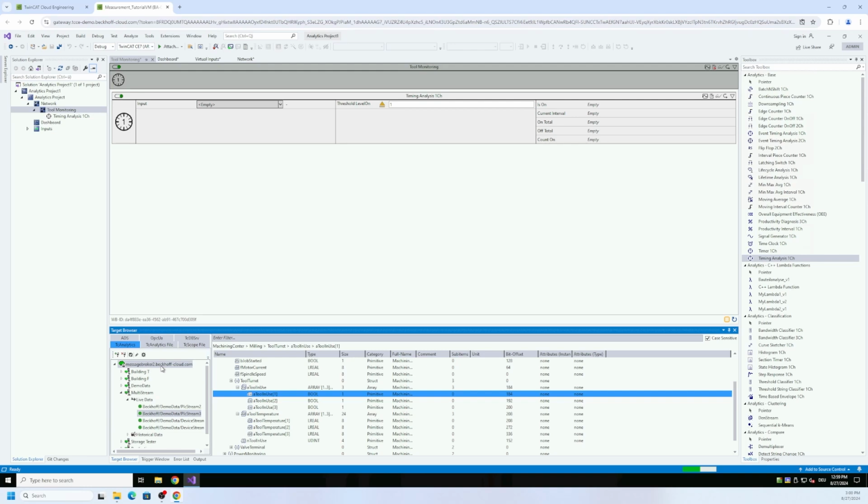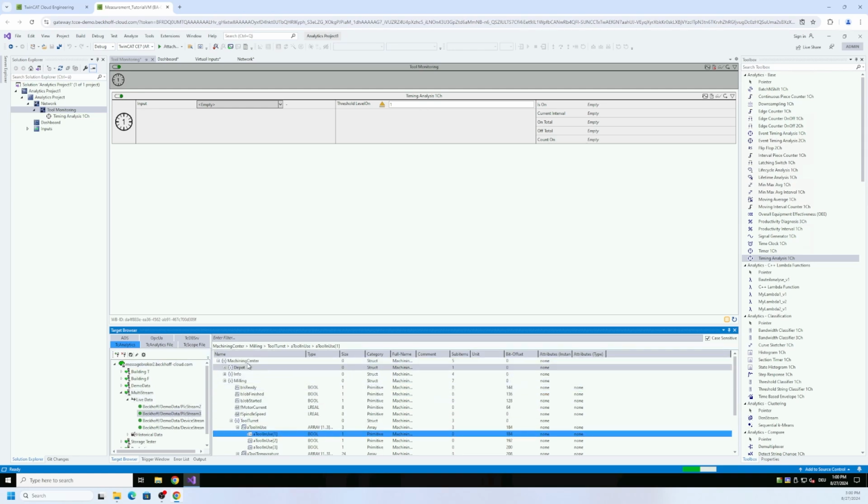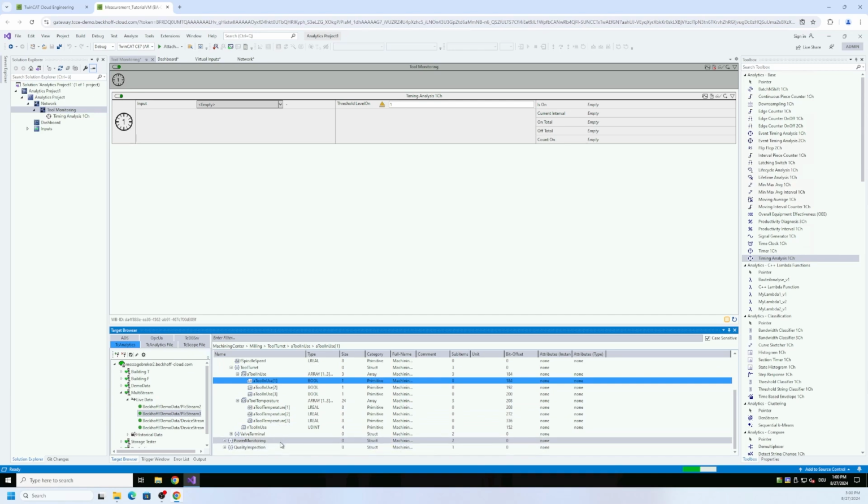In this case, it is our TwinCAT Analytics logger, which is a logging component in the real-time context of my machine application. In this case, it is just a small embedded controller with a simulation of this milling machine. And then the logger is providing the data via MQTT. And I can connect to the message broker, and I read out here the PLC stream where the data is in. So this is a machining center, and there it gives different categories like depot, info, milling, power monitoring, quality inspection, and other things.